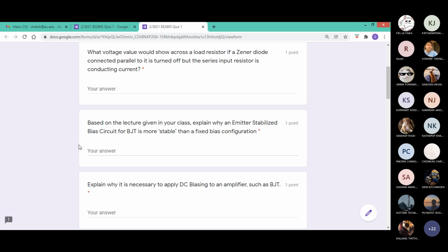We are concerned about the stability of output collector current and output collector-emitter voltage when the beta varies with temperature. But everyone is talking about stabilized base current. In some ways it is correct, but you had to explain further. If you have stabilized base current, what does that do to the output current? That part you did not tell.